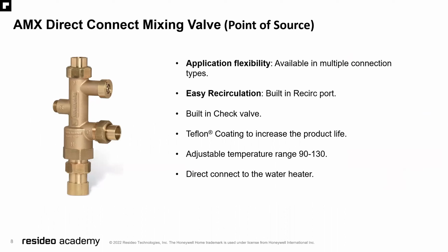We also have the AMX Direct Connect mixing valve, point of source. Application flexibility available in multiple connection types. Easy recirculation because it has a built-in recirc port. Built-in check valve, again, Teflon coating to increase the product life. And an adjustable temperature range of 90 to 130 degrees with a direct connect to the water heater.